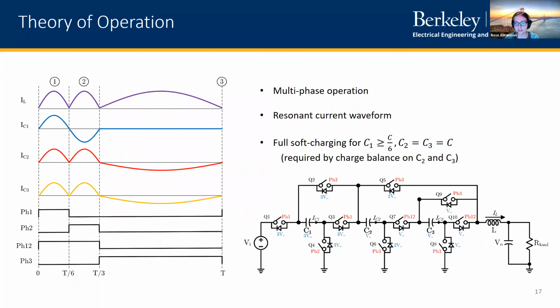Okay, so then just going back to this, to hold this converter topology in your mind, you can see that if we look at all the switch and capacitor voltage ratings, we don't really have anything above 3 V out. So for an 8 volt output, that's only around 24 volts, and it'll be higher if your input drifts a little higher, and lower if your input drifts lower. But it's not a huge demand on the switches.